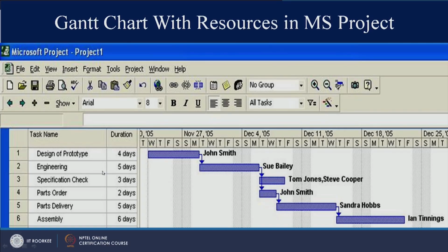If you look at engineering, it is taking 5 days, right. So, again first day, second, third, fourth and Saturday, Sunday. So, again Monday you are finishing it. Actually it is taking 5 days, you are not working on 2 days. So, while calculating the critical path of a project, you need to look at whether there is a holiday or not in a particular week, right.